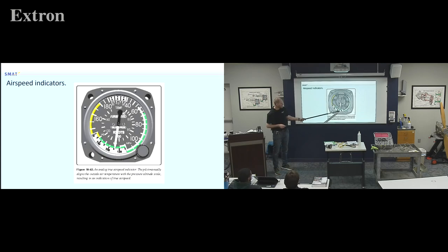Is that a 140 though? And this is a 140, so what's happening, if you look at this one close, we'll switch to one that's cleaner, is we can adjust this little section of the window based on the outdoor air temperature. Because remember, our temperature of our air, less dense, more dense, we're dealing with this ram air. So if we really want to be picky about how fast we're going, what we actually do is we say, what temperature is it outside? It'll be easier to show on a different one, but we'll line up our outside temperature.